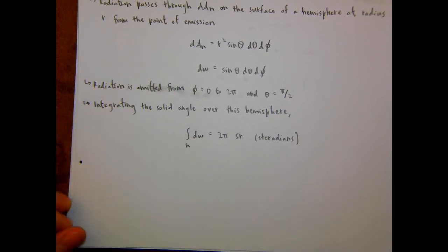All right, so for heat transfer, we're always curious about the rate of things. So we're going to talk first about the rate of emission, specifically the rate of heat transfer. The reason we introduced this hemispherical and differential area concept is because we first talk about the rate of heat transfer as far as how fast heat emitted from a certain point is passed through that differential area in the hemisphere.